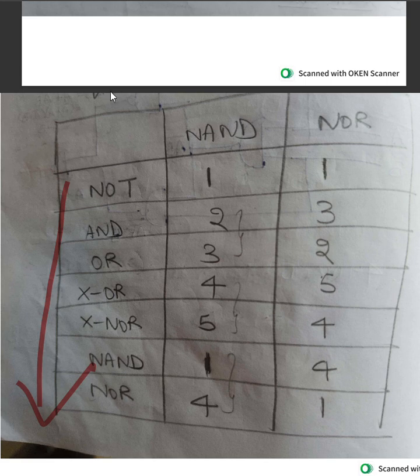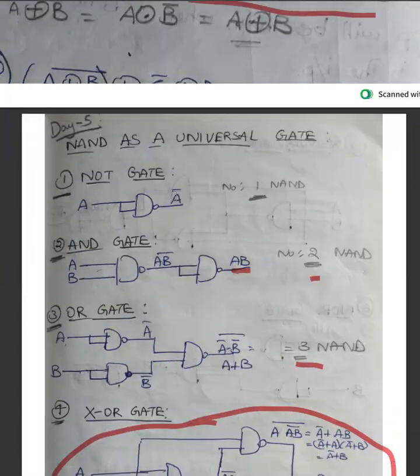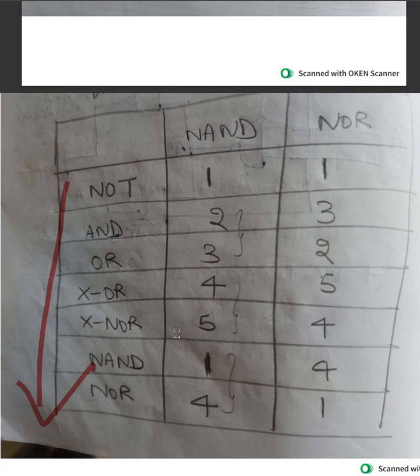So the trick is, you write NAND and NOR. Okay. So first order, the same order you have to follow. What order we followed? NOT, AND, OR. Okay. The same order we learnt as well. Remember that. NOT, AND, OR. So in NAND and NOR, in both of them, for implementing a NOT gate, you require a single NAND and a single NOR.